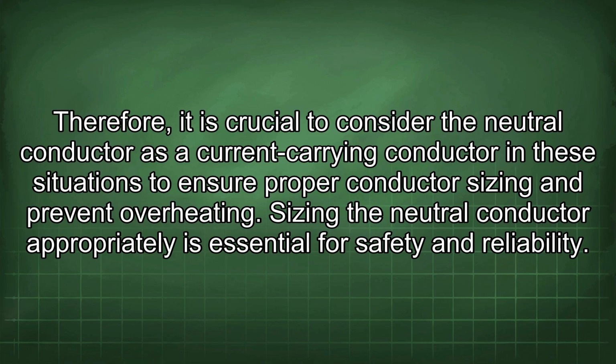Therefore, it is crucial to consider the neutral conductor as a current-carrying conductor in these situations to ensure proper conductor sizing and prevent overheating. Sizing the neutral conductor appropriately is essential for safety and reliability.